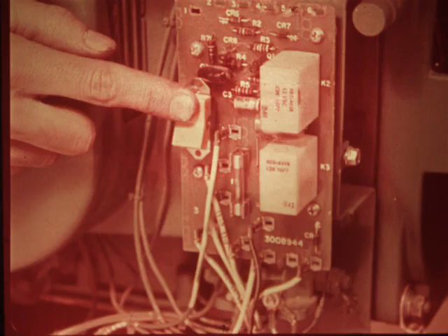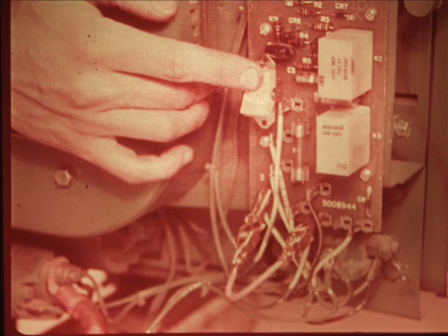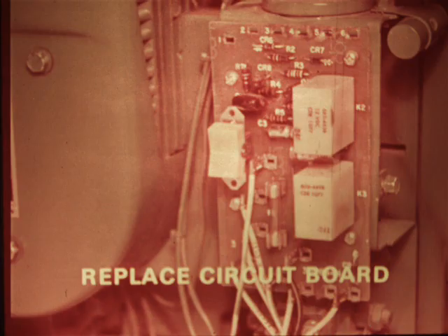So, connect the jumper between terminals 9 and 11 and operate the starter. The engine does start. Therefore, you can conclude that the relay contacts are defective and you should replace the printed circuit board. However, on older units, you might find the problem is simply dust in the non-sealed relays. So first, before you remove the circuit in older units, pull the caps on both relays and scrape the points with a knife blade.